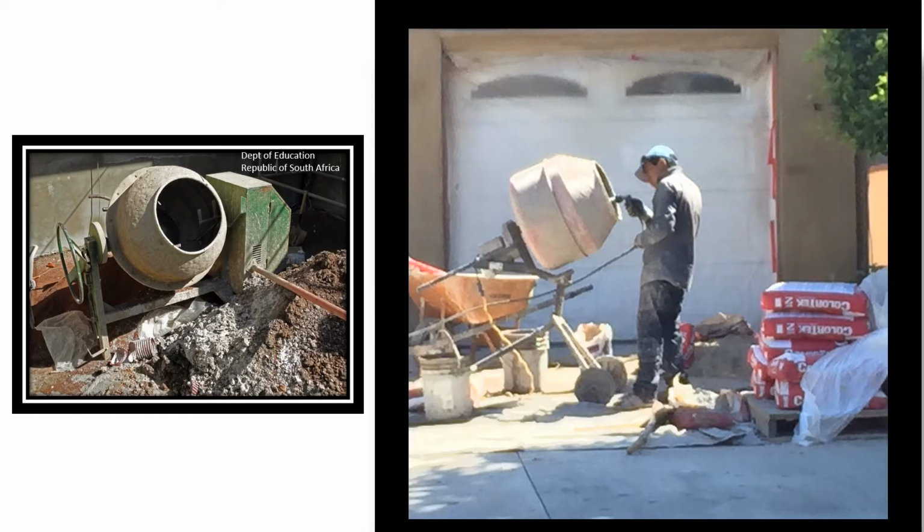The barrel style mixer is not recommended for use to mix cement plaster. This style of mixer relies on aggregates such as rocks found in concrete blends to help blend the mixture. Using this style of mixer can result in lumpy or inconsistent material mixing.